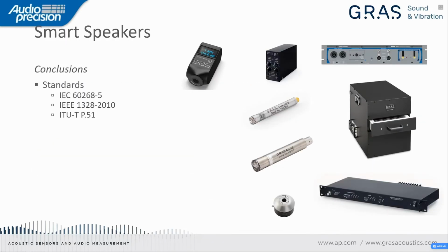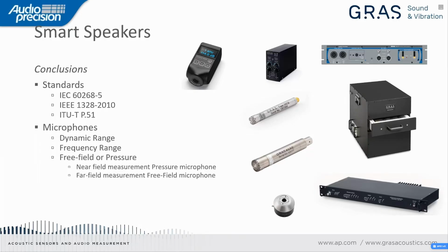Conclusions. When doing a smart speaker test, we have to do the test according to the standards: IEC 60268-5, IEEE 1329 from 2010, and ITU-T P.51 for our mouth simulator.